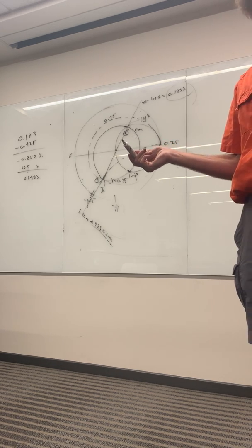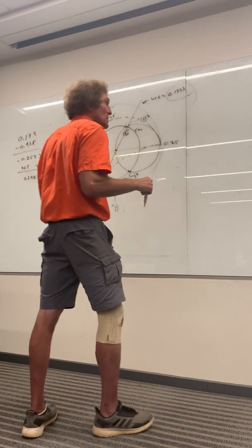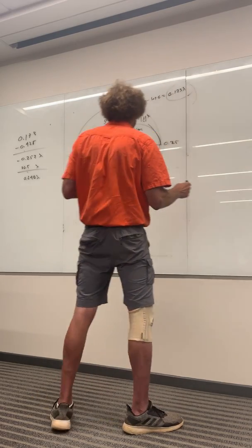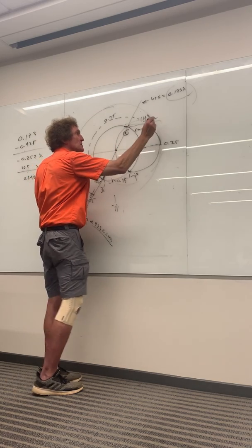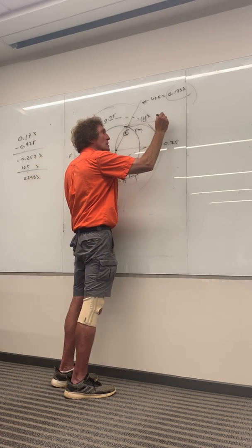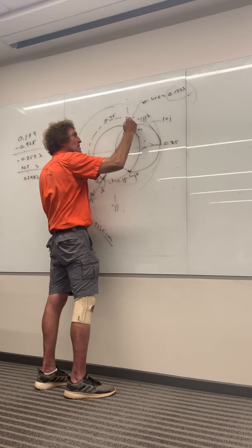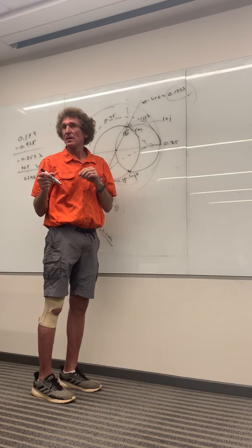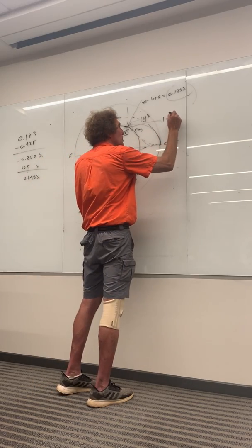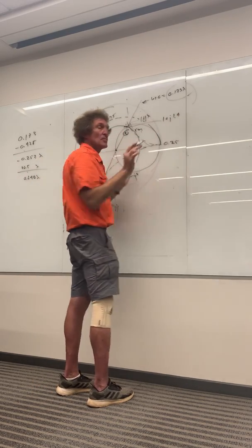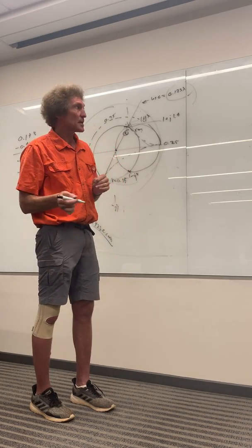All right, now work with me on this one. So that distance is there. Now, you've got to do this too. When I look at this point, I know the real value is 1, but what is the imaginary value? It's 1 plus j what? Take a look at that. It's going to be something like this. What is it? Can you confirm that? This is j what, 1.4? 1.4. All right, so it's j 1.4, and that's normalized, right? Yeah. All right, there's a couple ways to do this. I like to do it this way.